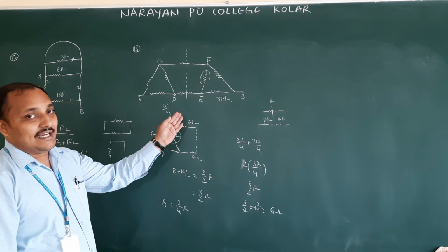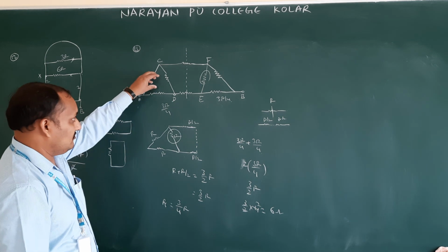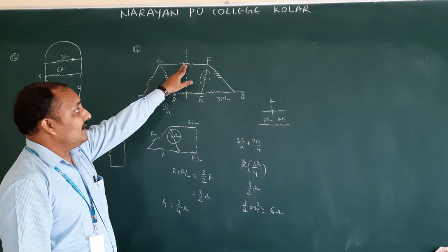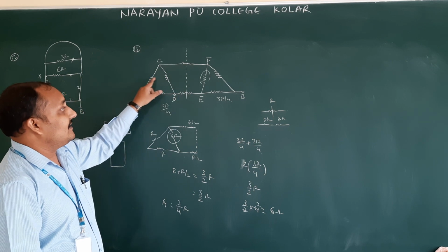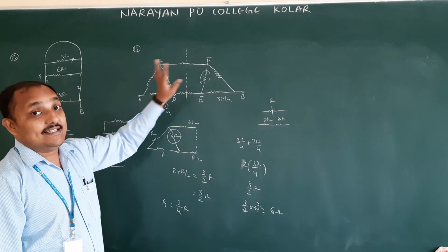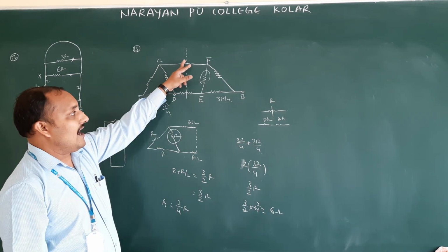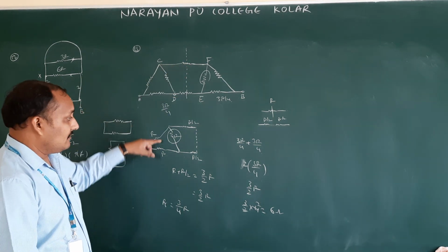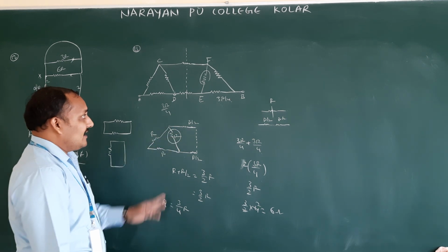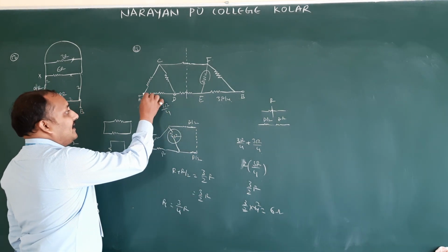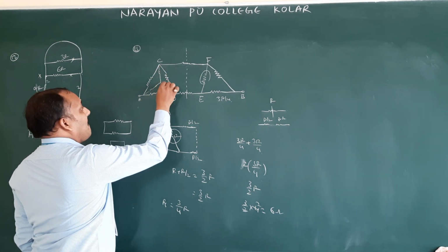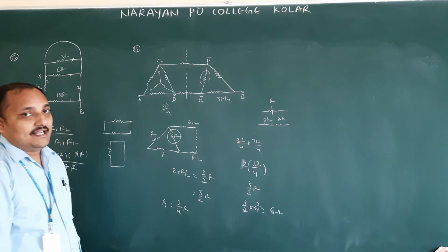Next, if you want to solve in another way, we start with the star delta connection. Compared to all those, this is the easiest. This will be applicable whenever all resistors are equal and the balancing condition is satisfied. So if they give R by 2, here we remove this one because the balancing condition is satisfied. Another method is the star delta connection, which we already discussed.